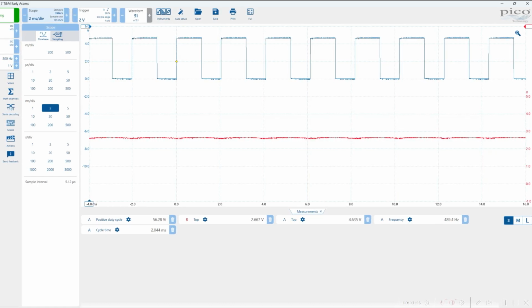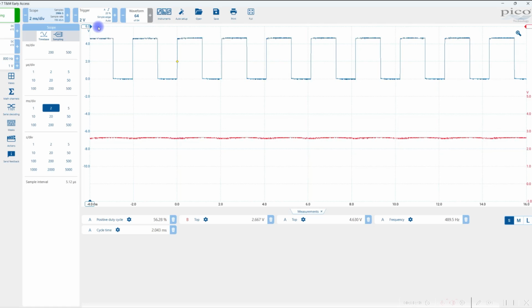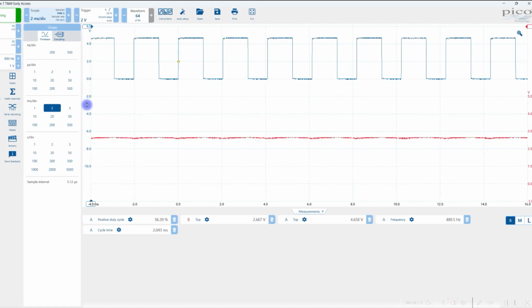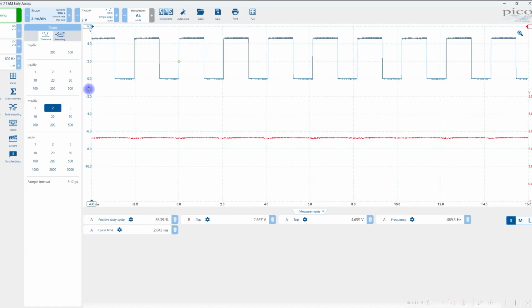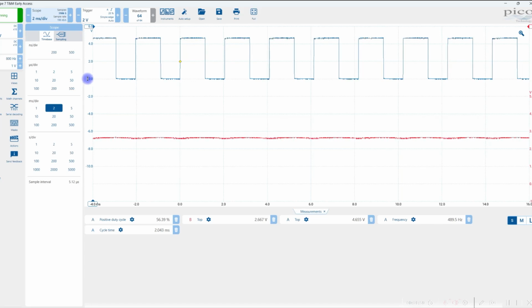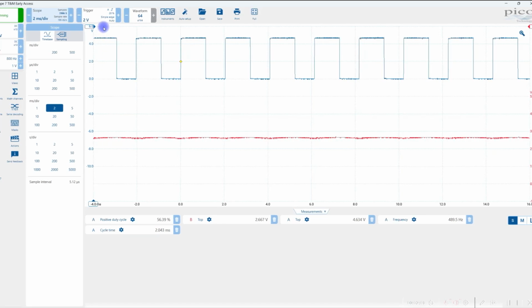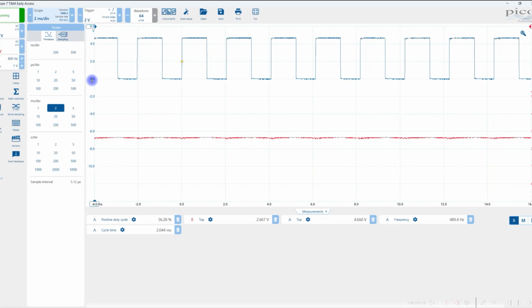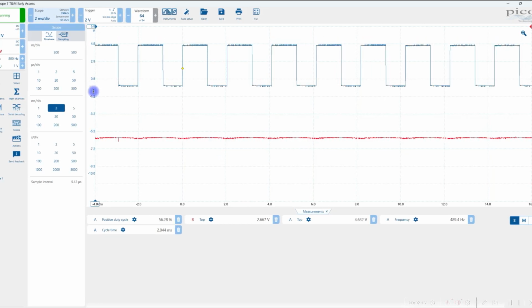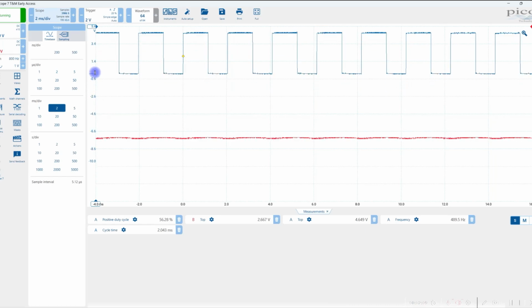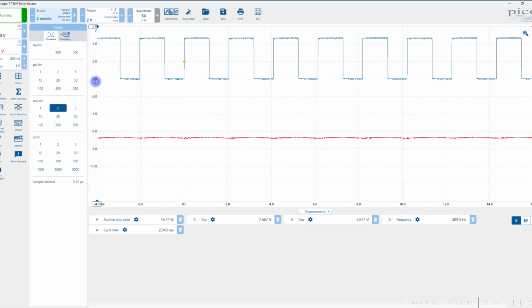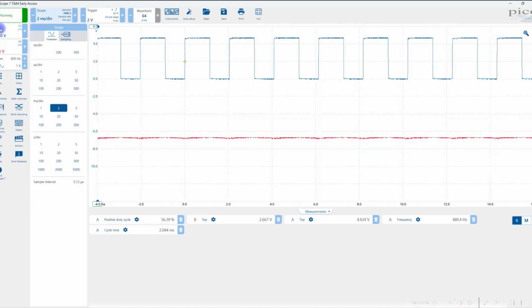So what that means is that it's plus 10 volts maximum and minus 10 volts minimum, but I've shifted the level of the signal a little bit. So what I want to have for this measurement is the zero reference to be maybe 3 of the divisions down. And I can adjust that just by coming over to this area with the number and moving my mouse up and down. Okay, but you want to have it set up so that 0 is on one of those lines. And that's for channel A.